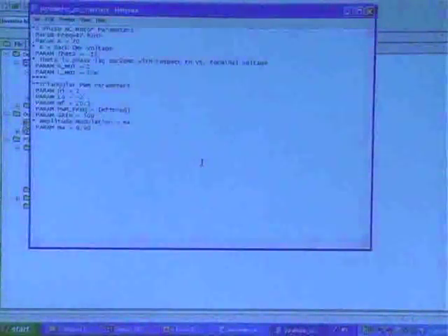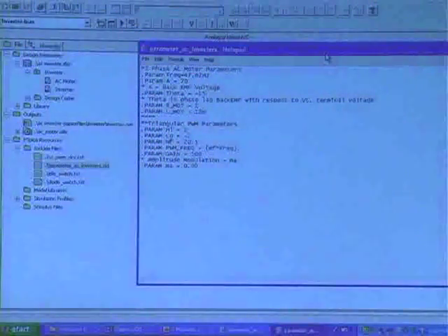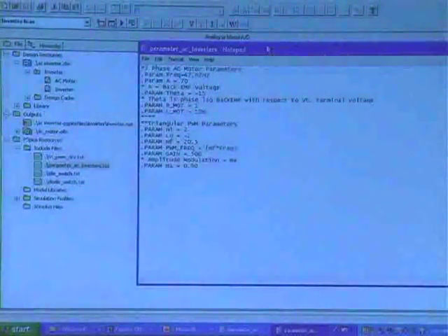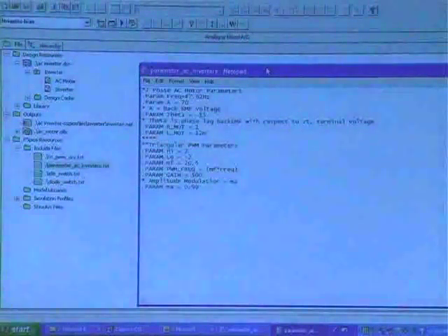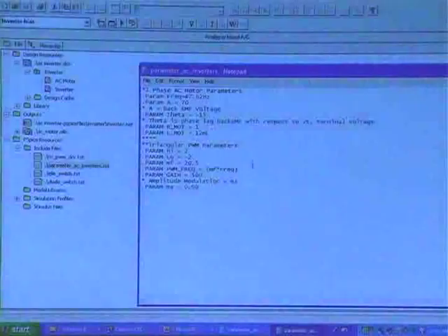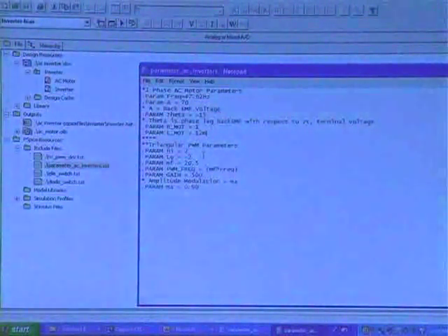Is this motor an induction motor? What does it represent? No, there's no electromagnetic torque. When we get to induction motor drives, then you'll see we do things quite differently there than we're doing here. This is just to illustrate the three-phase sinusoidal inverter. So we have 1 ohm resistance here, 12 millihenry inductance.